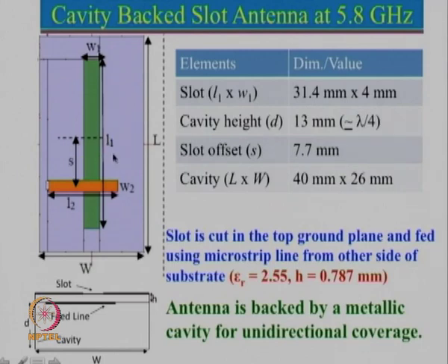Of course, we do not put it in the center because impedance will be high. So, generally the coaxial connector can be put over here, the outer cable will be put somewhere here, and the center pin can be connected to this other side here, and that way one can feed a simple slot antenna.